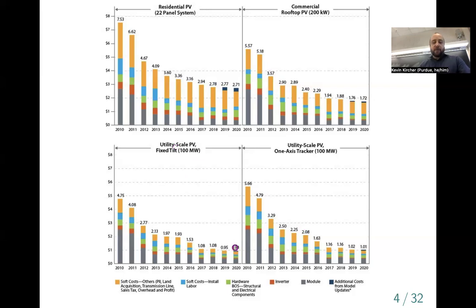And then this is for a fixed panel, basically something that you bolt in place and it never moves throughout its lifetime. You send someone out to maintain it periodically, but the panel itself is not moving during the day. And then this is with what's called one or single axis tracking. So here you might have a motor, or it might be a passive system that basically adjusts the positioning of the solar panel during the day to kind of track where the sun is in the sky. And so you can see that single axis tracking is only slightly more expensive today than a fixed axis. So we'll talk a little bit about, again, if you could orient the panel, how you might do that, and what angles you might choose at different times.